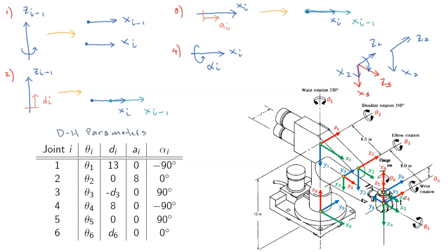As we have talked about earlier, in forward kinematics, one has to carry out a number of steps. First, we have to establish coordinate frames for every link of a robot arm. Next, we have to find the geometric link parameters. So for the first two steps, we follow the DH representation. The third step will be to find homogeneous transformation matrices representing the pose of coordinate frame i with respect to coordinate frame i minus 1.